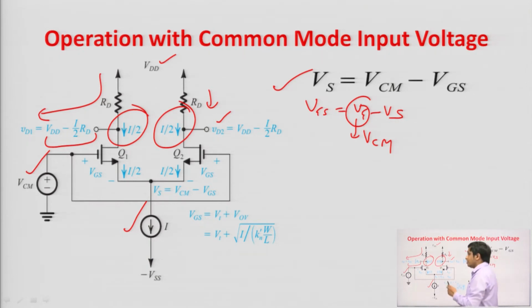It means that if any common mode signal is applied at the gate of Q1 and Q2 transistor, that common mode signal is noise signal, interference signal, then in that case the output is 0. So, that interference signal, noise signal, is not propagating to the output. So, here we can understand how this differential structure is rejecting the common mode signal, that noise signal and interference signal, right.